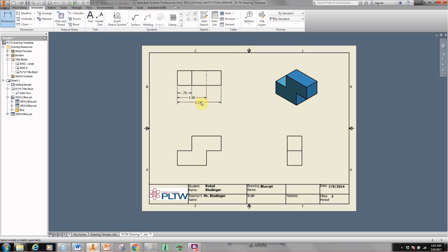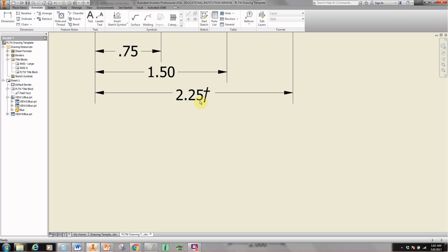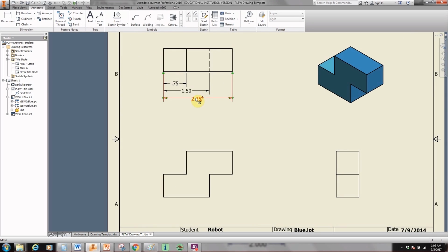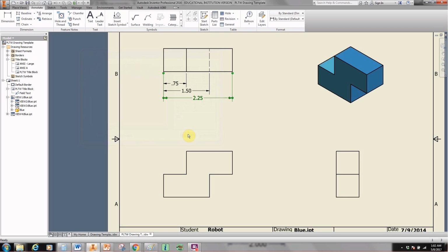But notice there was a little symbol showed up. Like I said, that sometimes happens. So to fix that, I had to click out and say OK. And when we go in, it looks like that 5 is even a little too small, but I guess it's okay. Double click on that, just come back, delete that little cross, and say OK. And there we go, that's properly dimensioned.